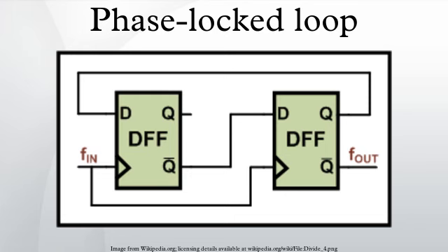Since initially the oscillator may be far from the reference frequency, practical phase detectors may also respond to frequency differences, so as to increase the lock-in range of allowable inputs. Depending on the application, either the output of the controlled oscillator, or the control signal to the oscillator, provides the useful output to the PLL system.